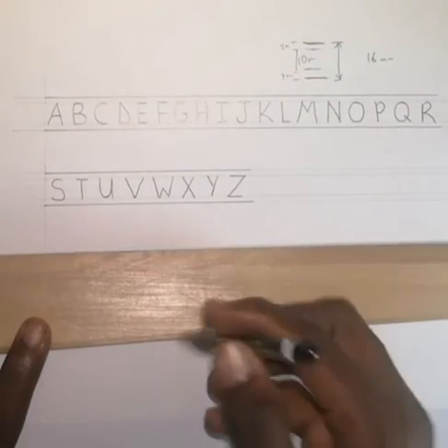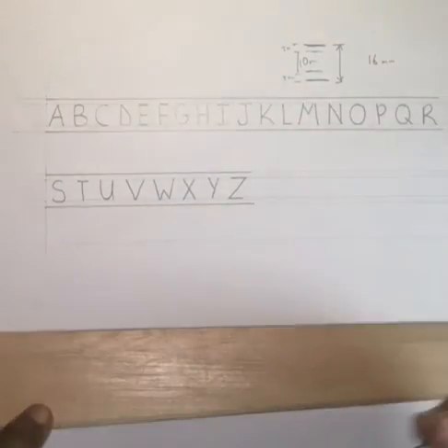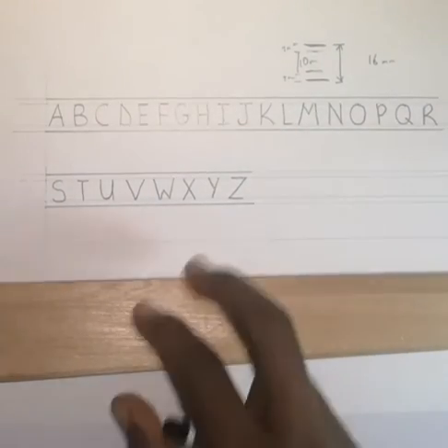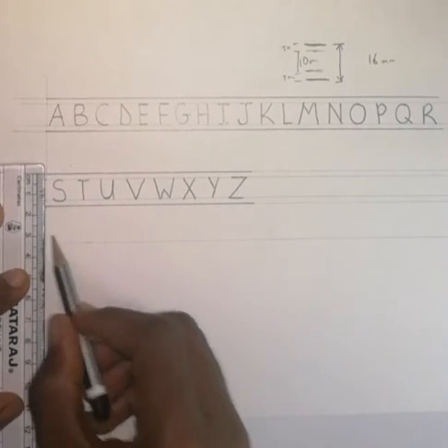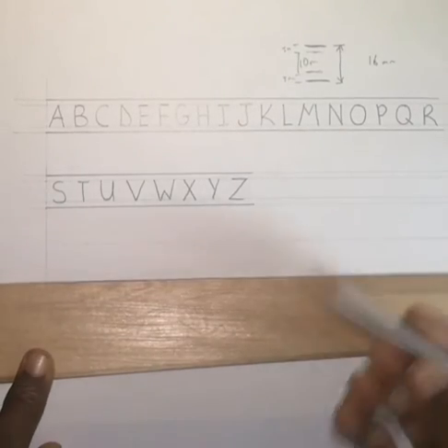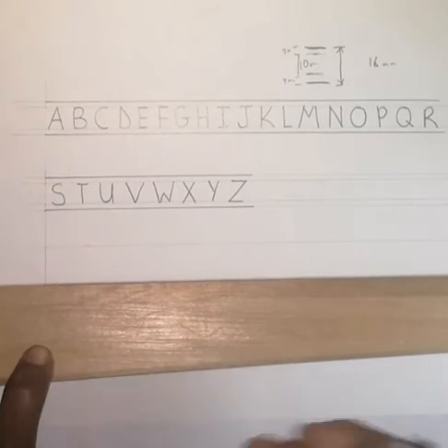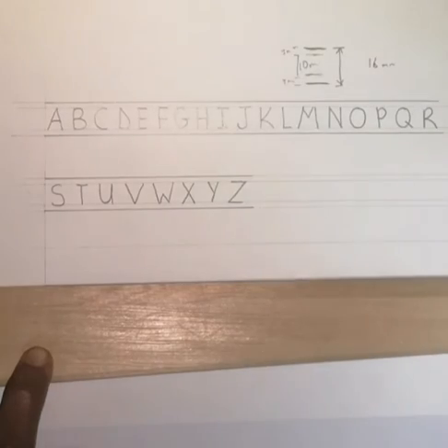Then you would go ahead to also number below. So take note, you can see I always draw thin lines first, then I use thick lines. This is the best and easiest way to draw, because if you make a mistake when you draw a thick line, as I've said, you would have problems with erasing. But if it's a thin line, you just leave it.